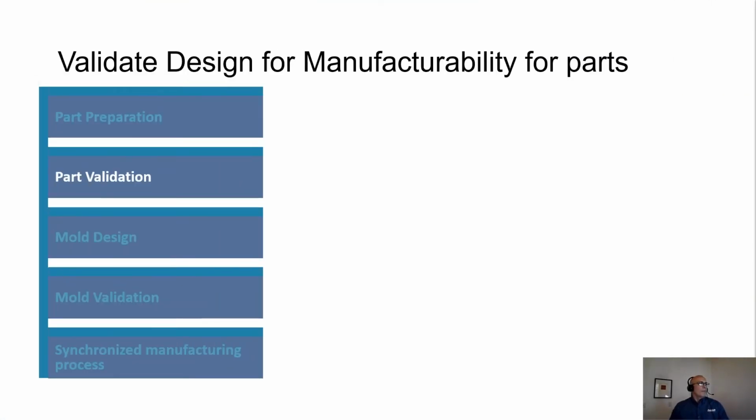All right, so NX has various tools that are going to help you ensure that your model and part quality is to the standard that you're used to. So you have the ability to analyze draft, shrinkage, parting lines, cooling, and many other options inside of there once you get in there and start working with it. In addition, it's integrated into Moldflow simulation.